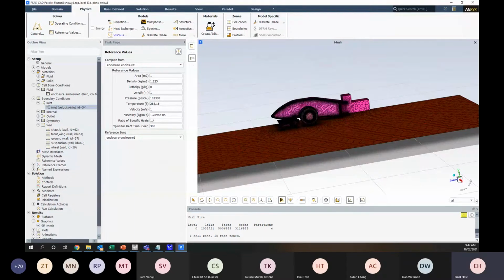Can we trust the results having reverse flow in 80% of the region? That's very case specific. You'll have to go to support for that one. You can just give a static pressure to your inlet, but it will be in terms of a gauge pressure generally, because we generally don't talk about static pressure as an absolute value, which is what it actually is. So in reality, we've got our atmospheric pressure, and any pressure that's forcing flow in a pipe will generally be something above atmospheric pressure, but we can just specify the gauge pressure.